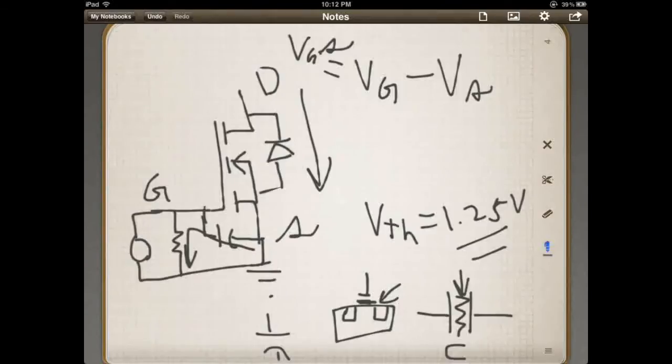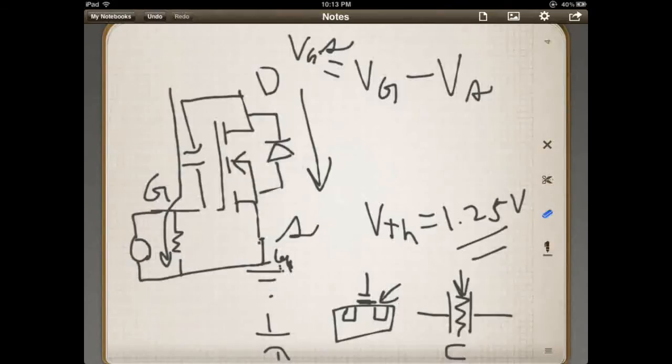And there's also capacitance here as well, between the drain. That's the one that you're bleeding the most of. This one will bleed off in this direction since it's already connected to ground. This guy, however, can't bleed to ground, but it can through this resistor. Sorry, I got it upside down here. So this one's not too big of a deal, even though it is there. There is capacitance there, so it may take a little bit to bleed it off.